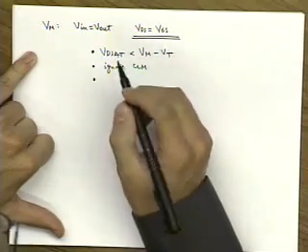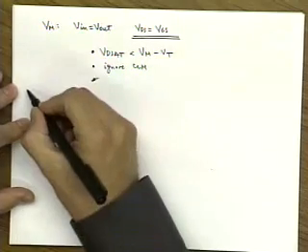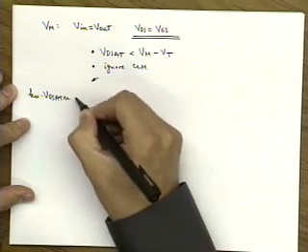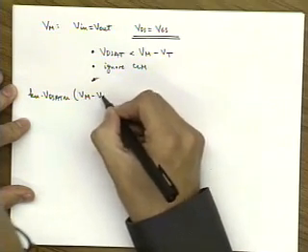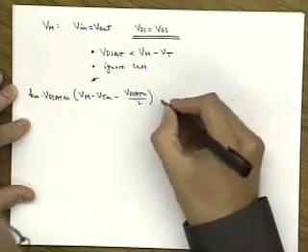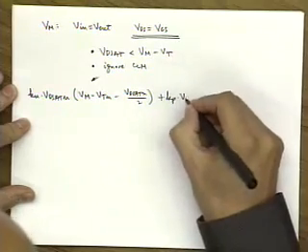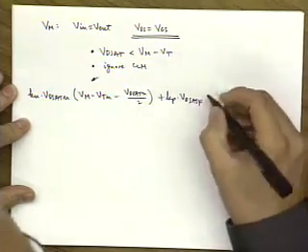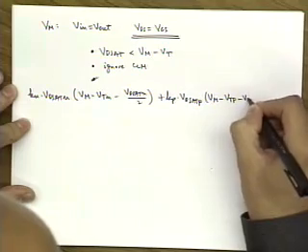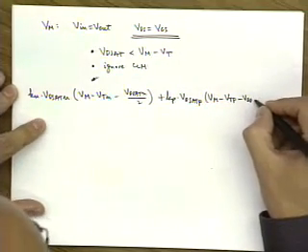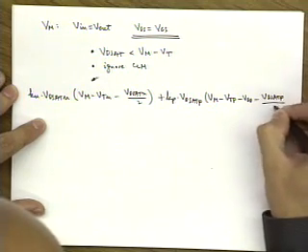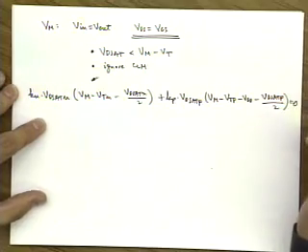And all we need to do now is make currents equal. So we have Kn times VD sat n times Vm minus Vtn minus VD sat n over 2, plus Kp times VD sat p times Vm minus Vtp minus VDD minus VD sat p over 2, equal to 0.